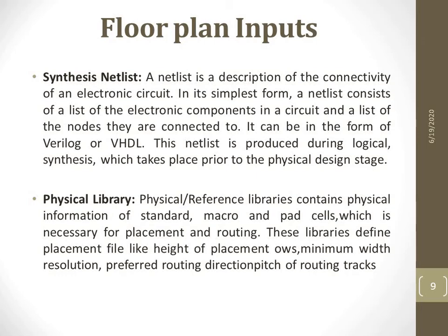Next is the physical library. Physical or reference libraries contain physical information of standard, macro and pad cells, which is necessary for placement and routing. So these libraries define placement information like height of the placement row, minimum width, resolution, preferred routing direction, pitch of routing tracks and so on.